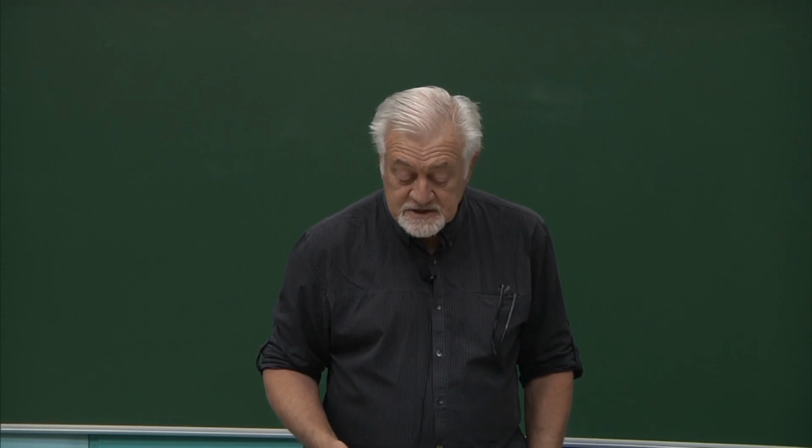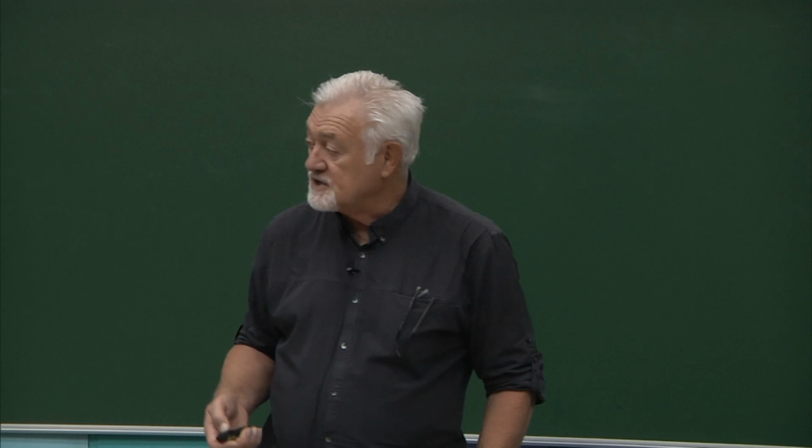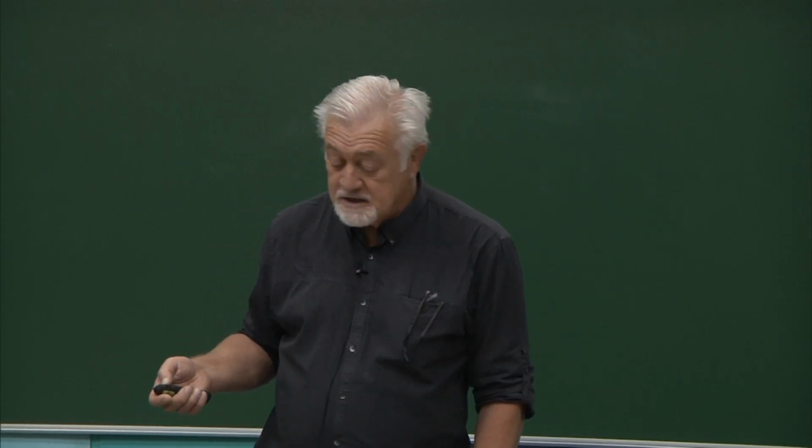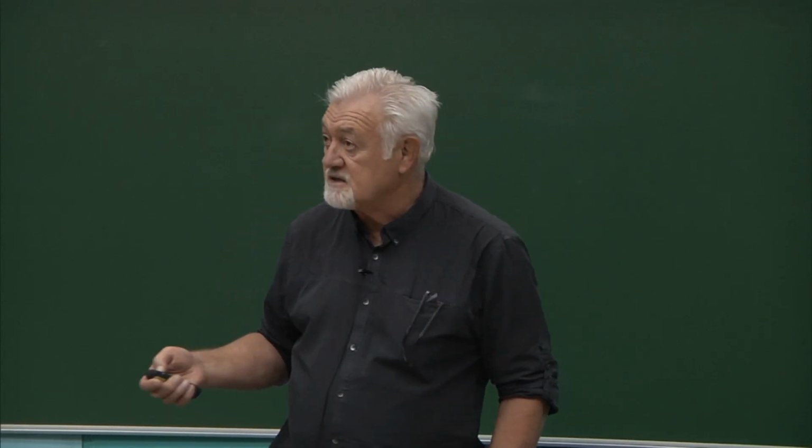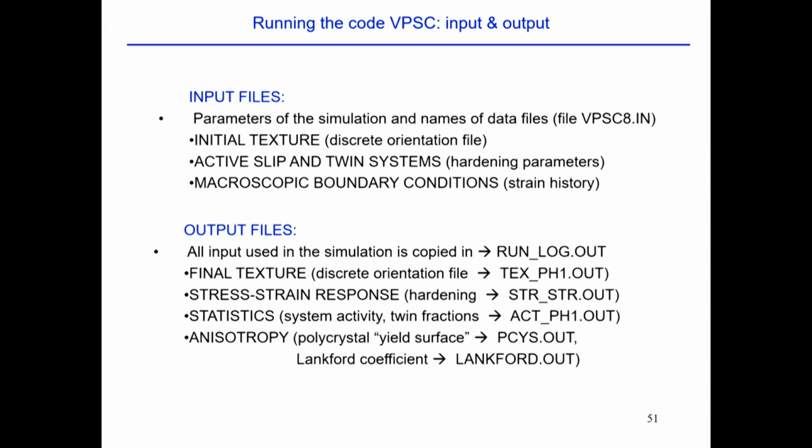So you will have a texture file, typically. You will have a file that tells the code what are the slip systems and the symmetry of the crystal that you want to solve, and what are the hardening parameters, that is the constitutive law. So on one side there is the crystallography, and after that the constitutive law in that file. And then the macroscopic boundary condition, which is which problem you want to solve.